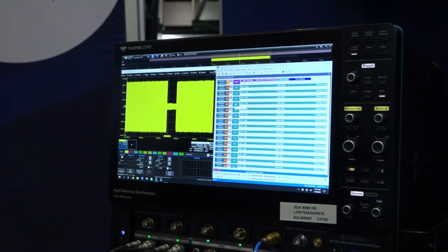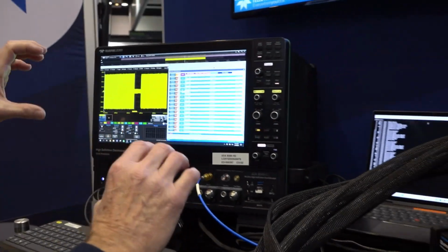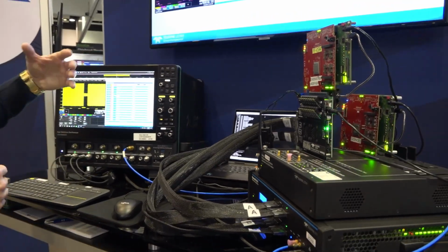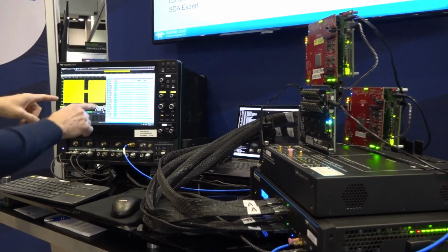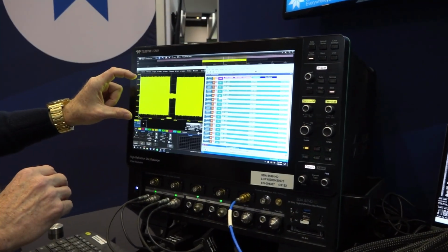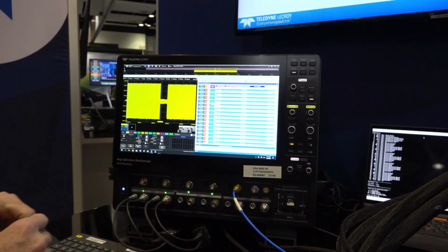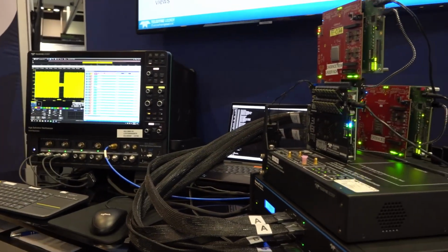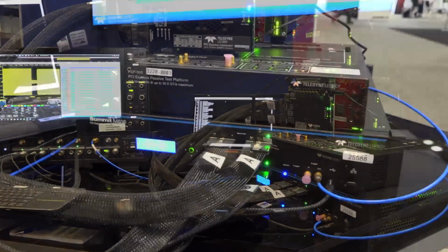And then the last step that we do is we have 2 sets of data, the protocol and the scope. We time align the two, and present that to the end user such that both tracers are on the screen, protocol and electrical, and they're time aligned. So this is a very useful debug feature for both functional test and electrical validation test.